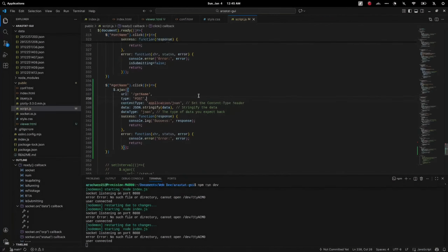But how do we capture the data? Here's how we visualize the data flow. First, the data flows from the microcontroller to our PC through UART. The data is translated from UART to USB packet so that it can be recognized as a local serial port. In the backend server, the incoming data is stored as backups and helps us to investigate if there are any anomalies in either our devices or the app.